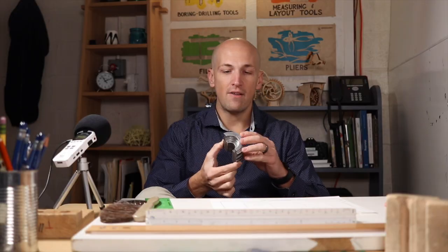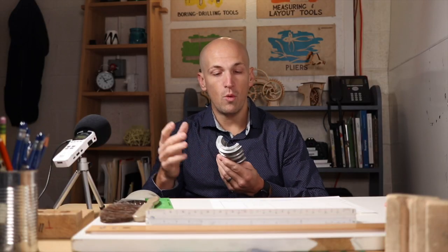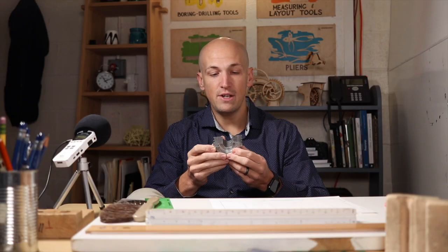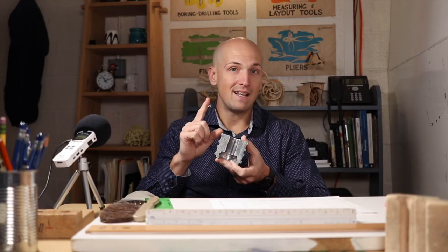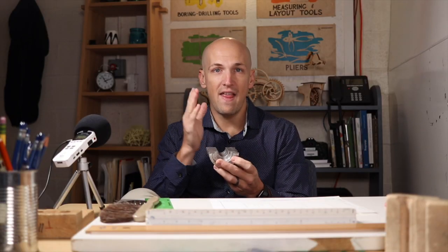When dimensioning anything, the whole point is to clearly communicate the part. So we use a terminology and a basic language when doing so. If your goal was to make this part, it is essential that you give all the dimensions necessary, not only to know the sizes of the part, but what materials it's going to be made out of, any special treatment this alloy needs to be treated with, and then also any special features where if this is my datum, the reference edge that I need to reference for all of it, or the center axis, that is essential to notate on your sheet or your technical drawing.